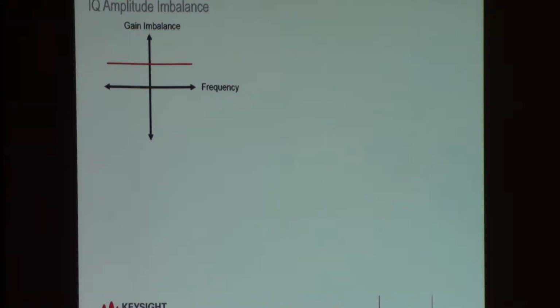On signal generators, you often have a control to adjust the gain balance. So you can imagine, I'll just decrease the I or Q gain to bring this back to 0 so that the response is perfectly the same between I and Q. And you could do that.